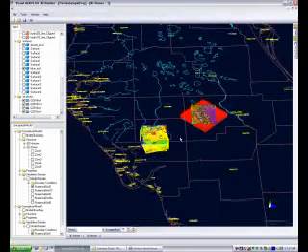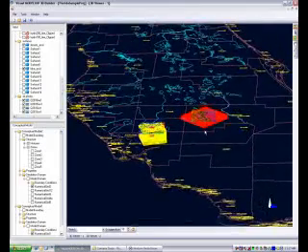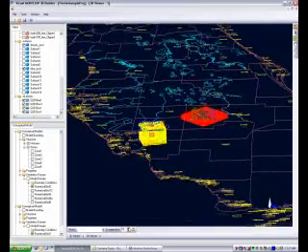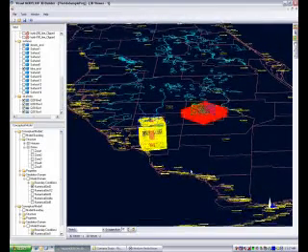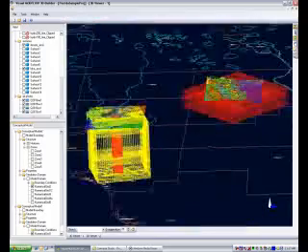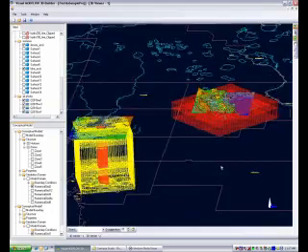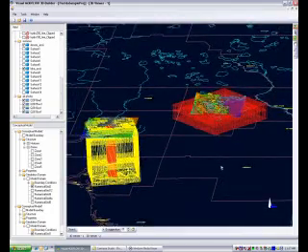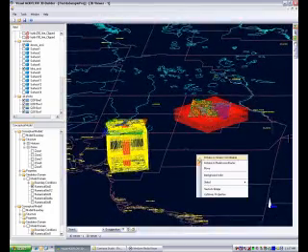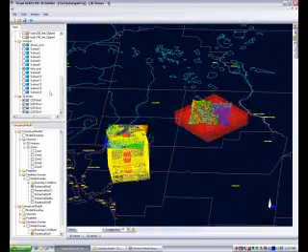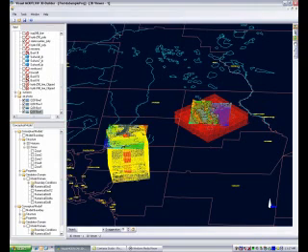So with this mapping environment, it makes it easier for you to design your grid and see where your model exists with respect to background rivers and roads, etc. So there's less number of times you have to go back and forth with your GIS programs. The lines here now show the set of rivers that I defined as for river boundary condition in the numerical model.